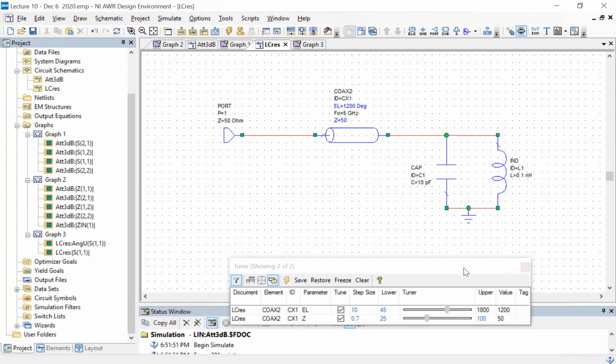So we have, I think, one pin diode switch, but that's actually for room temperature operation. Again, that's the problem with cryogenic things. Not all electronics actually work because the carriers just freeze out, and then the standard silicon electronics don't work. But there are actually a lot of off-the-shelf components available which still work at low temperatures. And often at lower temperatures, they work at very different bias points and all, but they do exist.